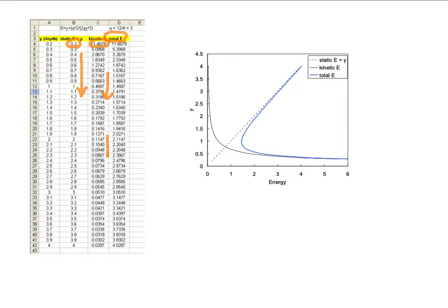So what is the rationale of this? Because the flow rate is always constant. So if your y is increased, it means the cross-sectional area is increased. To balance the continuity equation, the velocity, or the kinetic energy, must naturally be reduced.